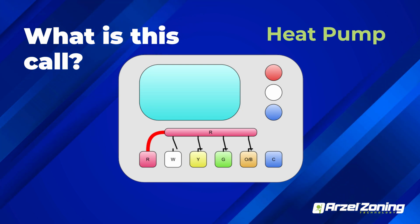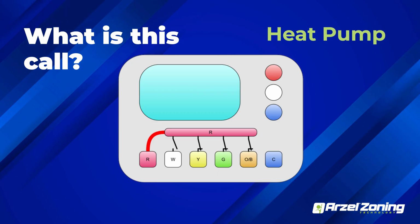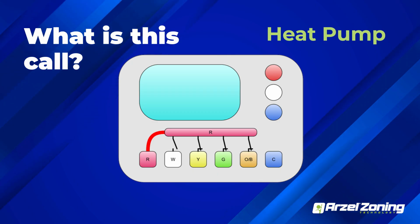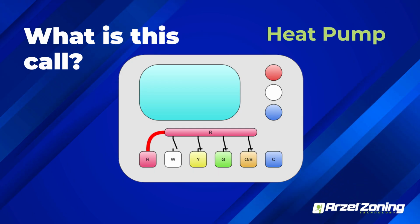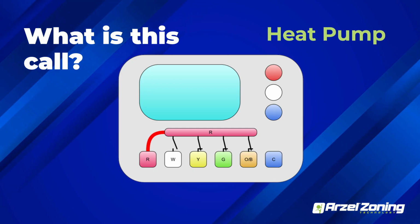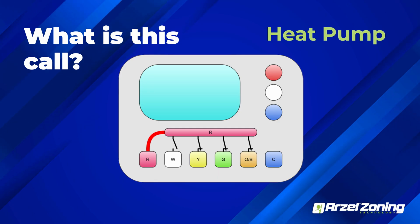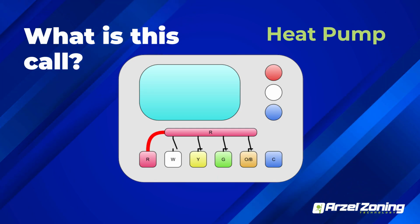So something to keep in mind with the Arzel panel, from the thermostat, doesn't matter what Arzel panel you are using, your reversing valve is always energized on a call for cooling from the thermostat itself. So when I have a thermostat, I have a heat pump system. If my O terminal from the thermostat is energized, that has to be a cooling call.